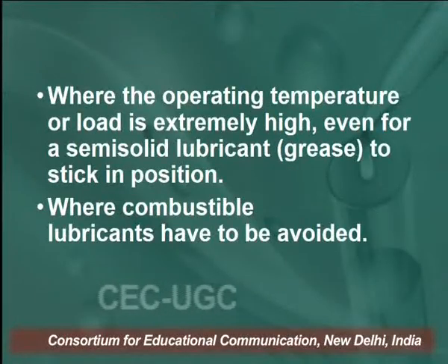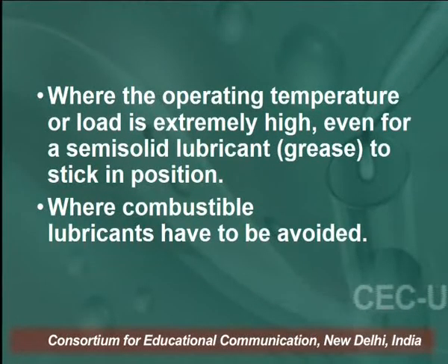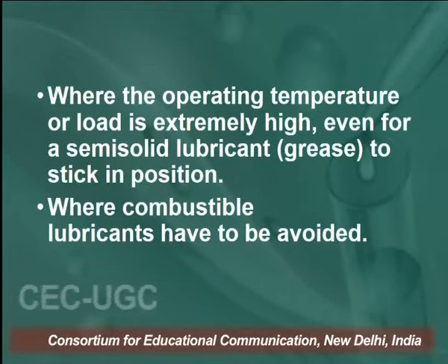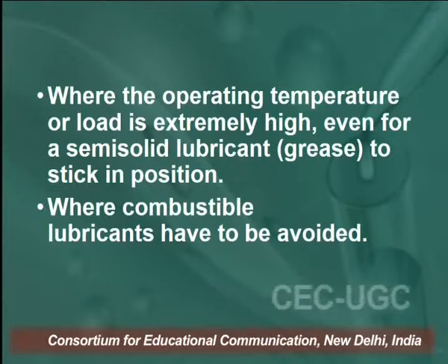Solid lubricants are used where the operating temperature or load is extremely high, even for a semi-solid lubricant like grease to stick in position. It is also used where combustible lubricants have to be avoided.